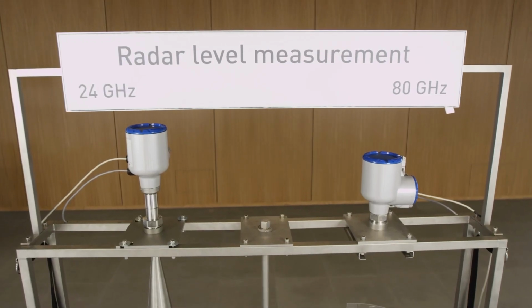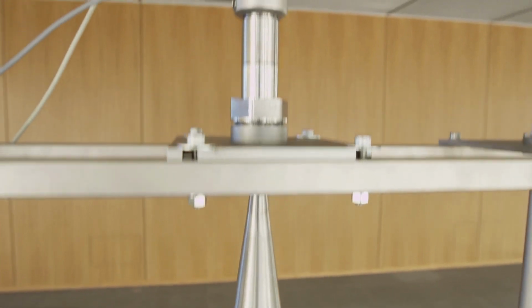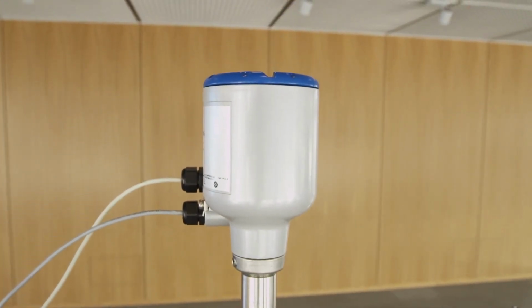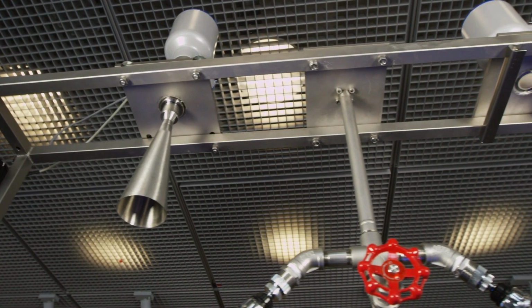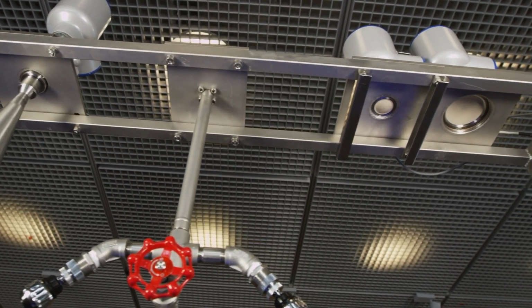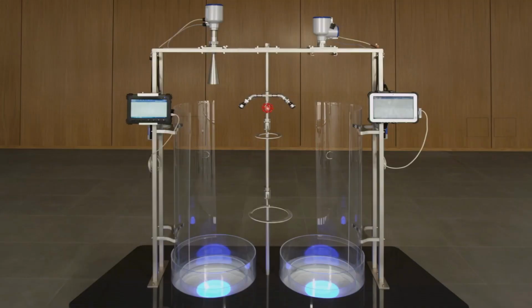The radiation pattern of a radar system results from the combination of the frequency and the antenna diameter. In general, the following applies. With the same antenna diameter, the beam angle decreases proportionally when increasing the frequency. At the same frequency, the beam angle decreases proportionally when increasing the antenna diameter.